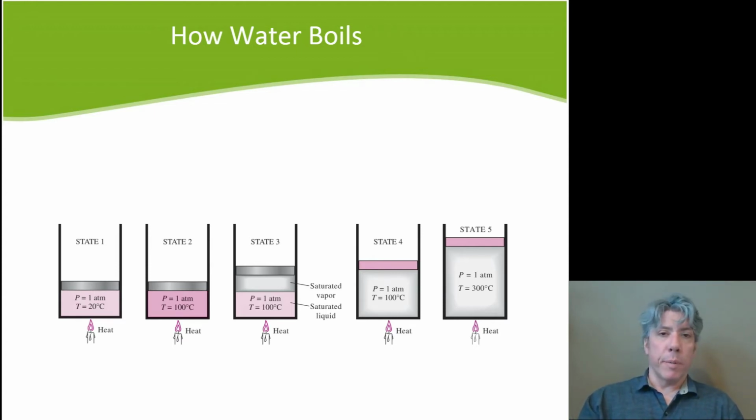And so thermal equilibrium is what we're assuming. Now, if you do this experiment at home and you boil some water on the stove and you stick a thermometer in the water, you'll find that it's 100 degrees. If you stick that same thermometer in the steam, if you were measuring just the steam temperature, you would find that that steam was at 100 degrees. However, what you will find is that your thermometer will drop, and the reason it drops is because the steam is not only steam. Rather, the steam has already mixed with air, and the reason you can see it is because it's already given off some energy to the air. It has condensed. That's what you see, teeny tiny droplets.